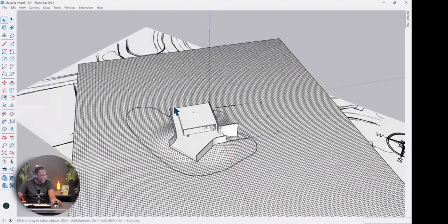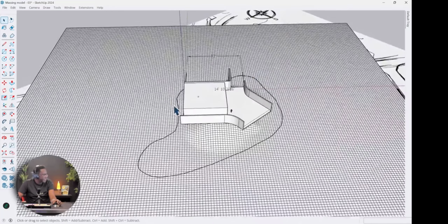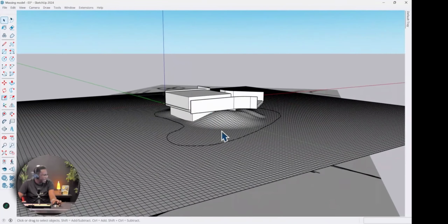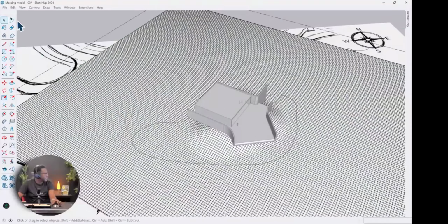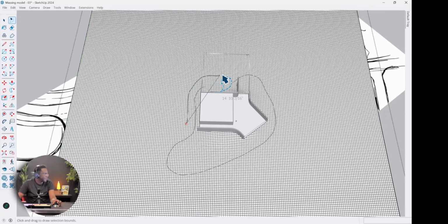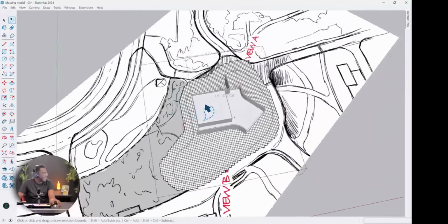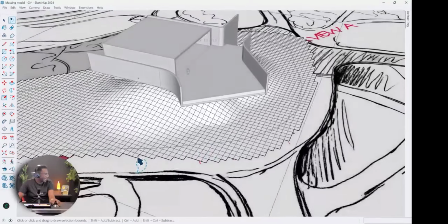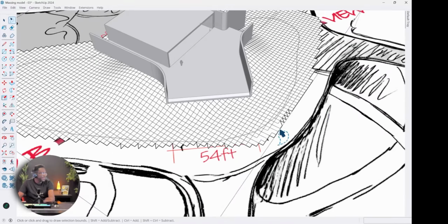Now, what we want to do is get rid of some of these detail squares, because we only needed them to create this little hill that's here. So to do that, I'm going to go into this group, and I'm going to use the lasso select tool, and draw around roughly this area here. Then I'm going to go to edit, choose invert selection, and hit delete, and that's going to delete a lot of the excess details that we don't need. And I can even go in and maybe trim this up some more, maybe like that.